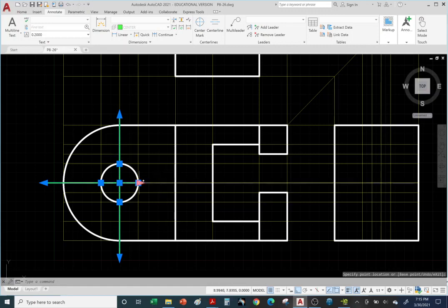All right, and let's extend. Oh, went too far, way too far. Let me turn off object snap so I can have control over that extension line. Okay, hit escape. Now in this case, we're not going to overextend the green center line because the top is not symmetrical to the bottom. As you can see, it's not symmetrical. Okay, so we'll leave it the way it is.